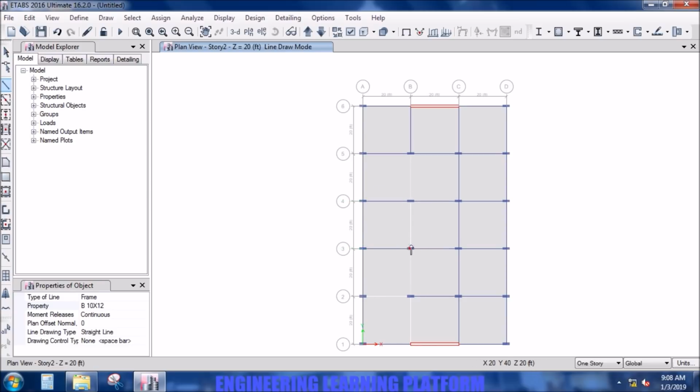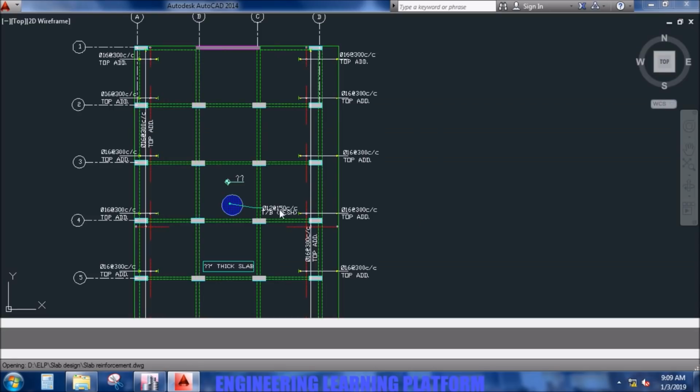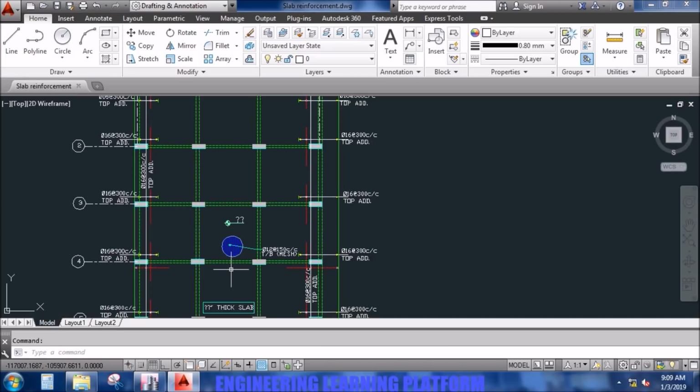It is also important that the slab forms a connection with the beams so that the load will transfer from slab to beams and then beams to columns. Make sure that the transfer path is complete. For the cantilever part, we need the dimension of the cantilever part.